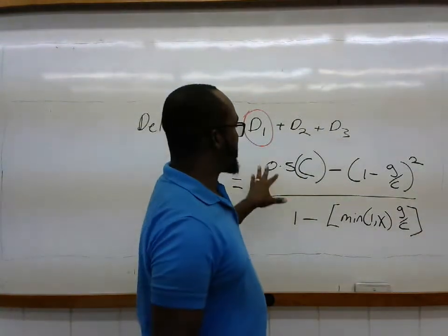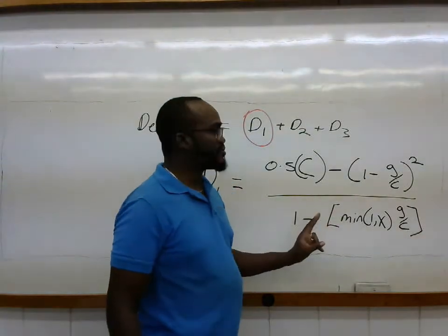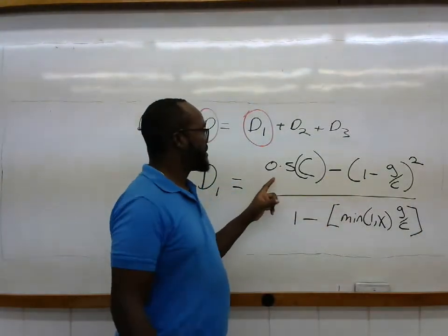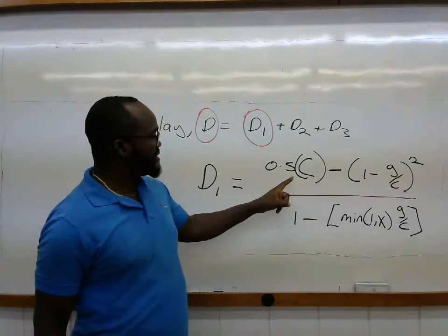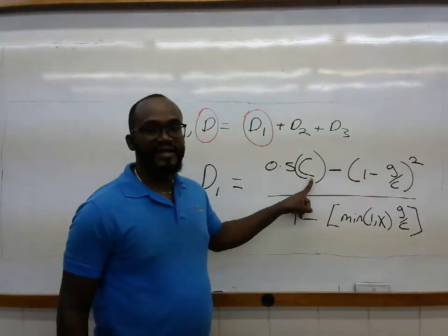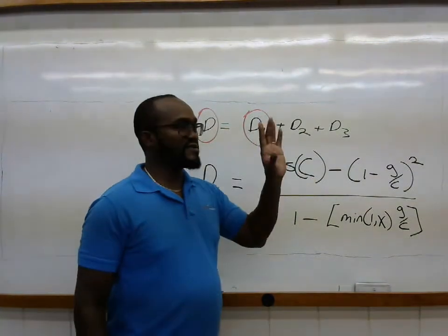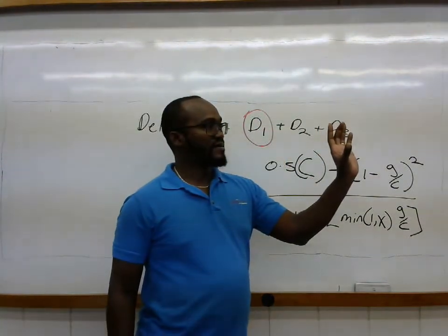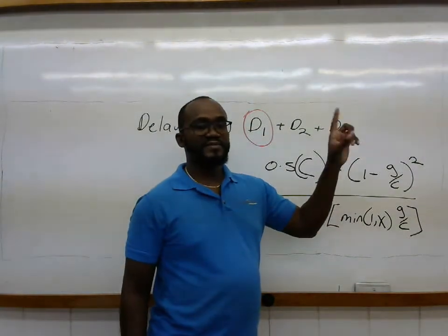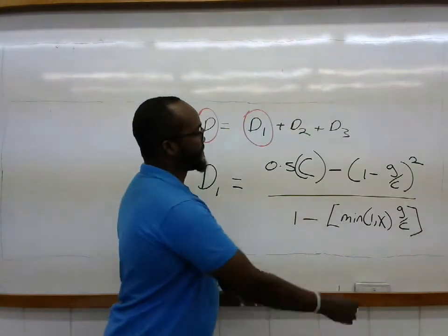After explaining, I'll go through the definitions of all of these terms, so you actually have those in your notes. But essentially, C here, big C, is what we refer to as the cycle length. What is the cycle length? That is the time from the red interval to a subsequent red interval. And I'll explain that in a little bit more detail subsequently.